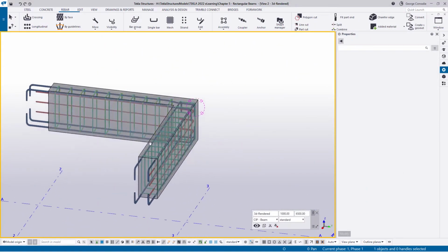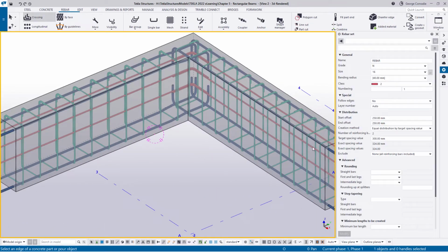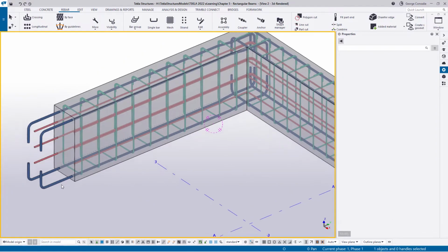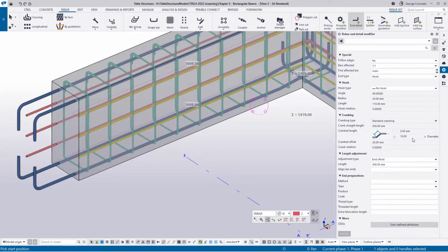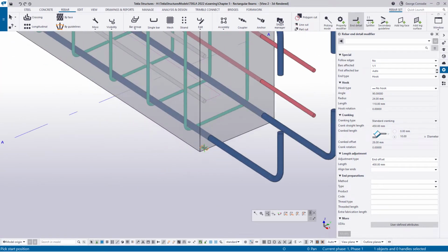Now all we need to do is look at the distribution steel on the inside. And for that, we can use the crossing bar again. And since the settings are the same, I'm just going to click and then pick this leg. And I'm going to pick that leg and say OK. And that will give us a big, massive L bar. And then what I'm going to do is I'm going to pick this bar. And while we've got our end modifier set to 400 extend, I might as well pick this edge. It extends it without a hook. And pick this edge. It extends without a hook.